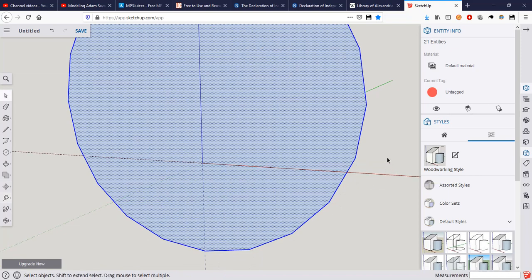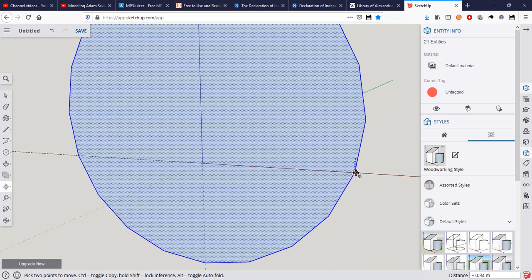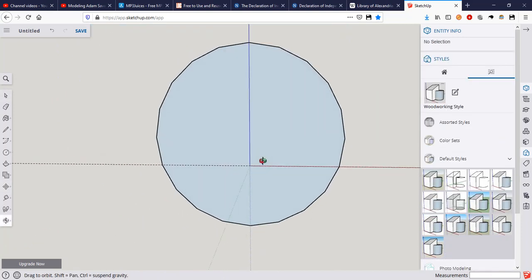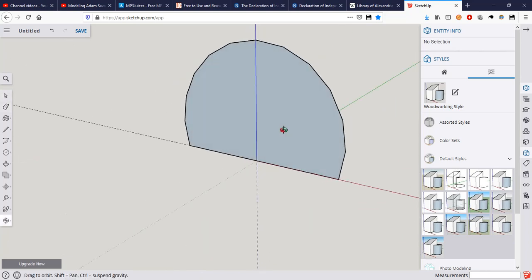So when we click this point and go on the down arrow, it's constrained to that line. Okay, perfect. So I think that's going to work. Let's go ahead and take our line tool, L for line, draw a line straight across right there. E for eraser, just going to cut that. Okay, so this is kind of what we have right now.